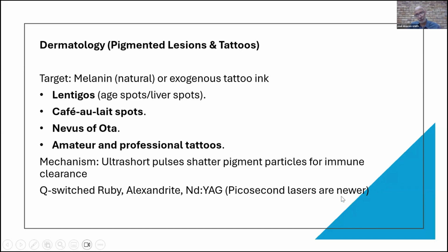Picosecond lasers are newer. So these are really fast pulse lasers. So you can see your Q-switch is typically 4 nanoseconds and so on, along that length of time. Your Nd:YAG tends to be tens of nanoseconds, but again, still equivalent, and they're really good, really fast. Remember, you're doing massive destruction, okay?